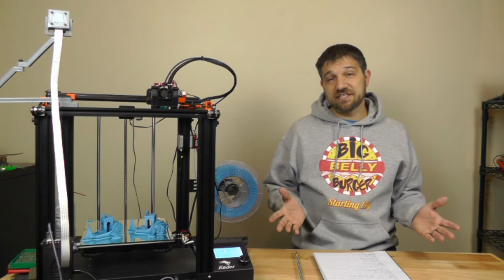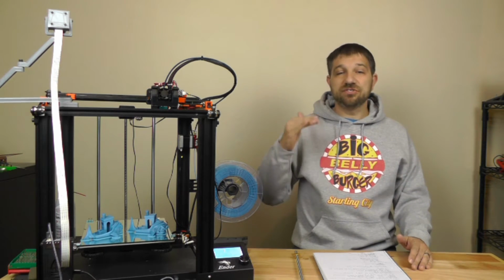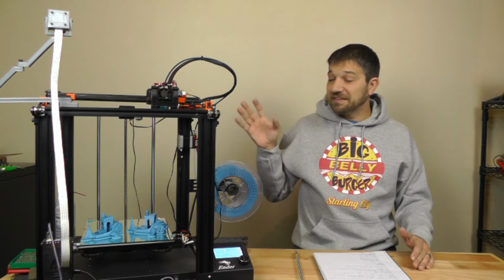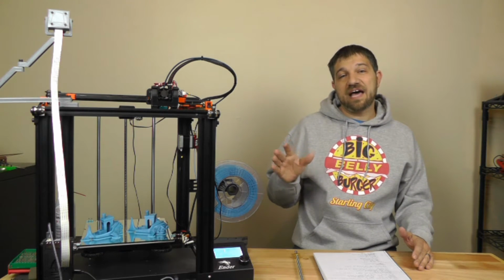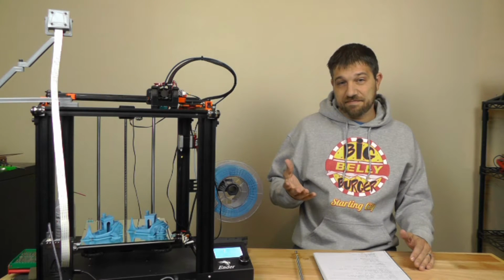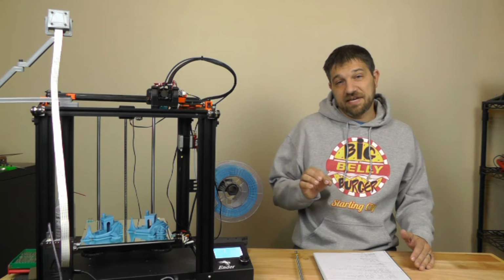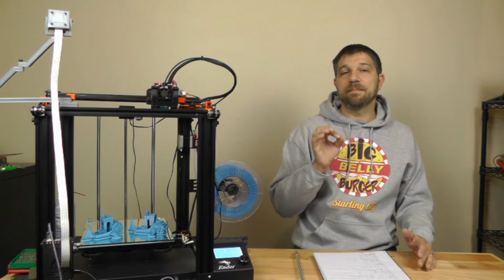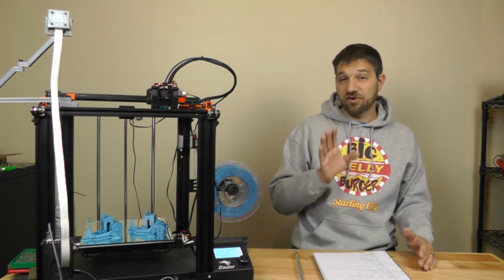So how do we fix this? Well, we obviously are going to decrease the angle of that hill. And to do that, we put a lead screw on here that's going to have much less of a lead. Now the pitch is going to stay the same. And so what that's going to mean is that we're also going to have to modify our firmware here because our number of steps per millimeter are going to change.